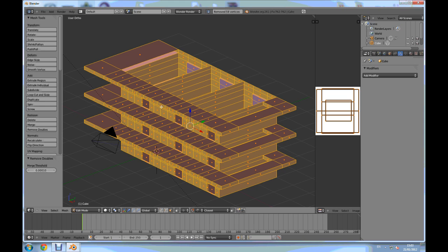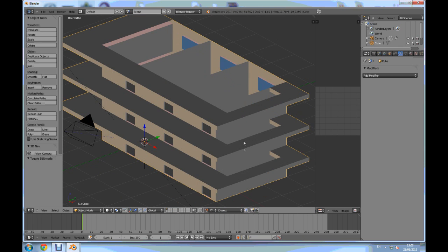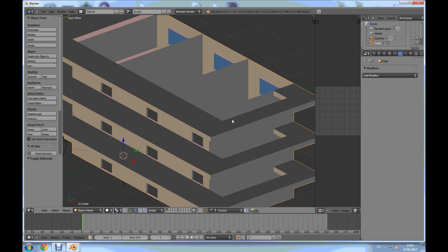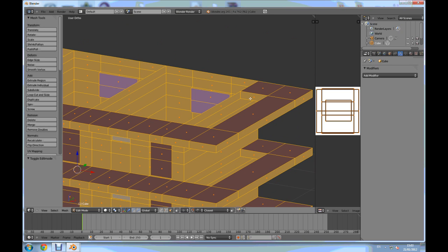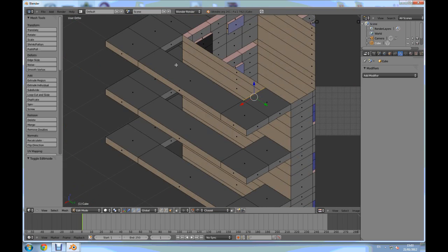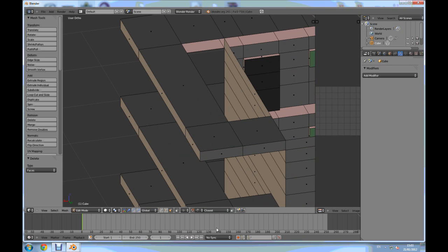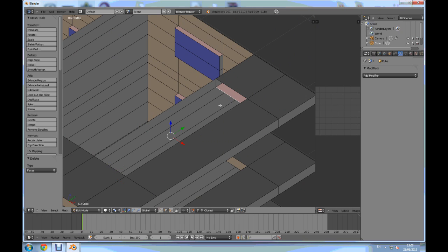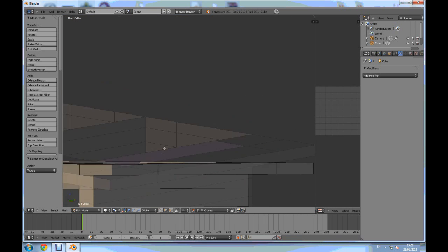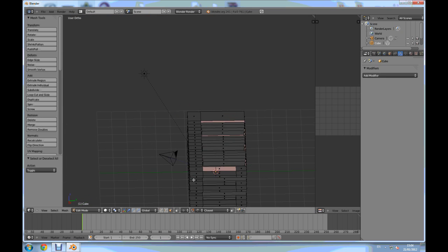What? Yeah, 58. Unbelievable. Alright, so we need to fix the roof now. As you can see, these are openings for stairs, but we won't need the stairs here at the top area portion, so we'll just close it by first maybe deleting the extra faces, because we are trying to keep amount of faces down. So select those 3, delete faces. Now go to edge selection mode, select this one and this one, and press F to fill the whole 1 and 2. F again. Yeah, but the material is wrong. It doesn't really matter because we will delete all these faces as well soon.